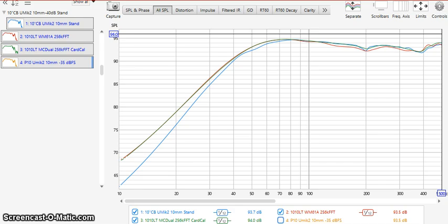What I'm going to show you is what I found that is, at least in my experience, an issue, at least with using REW, the Room EQ Wizard, to measure close mic near field measurements. And I say close mic because near field is a broad range. There's a transition between near field and far field, and it extends quite a ways out from the driver, which is dependent on driver diameter and the frequency involved, so it varies with both.